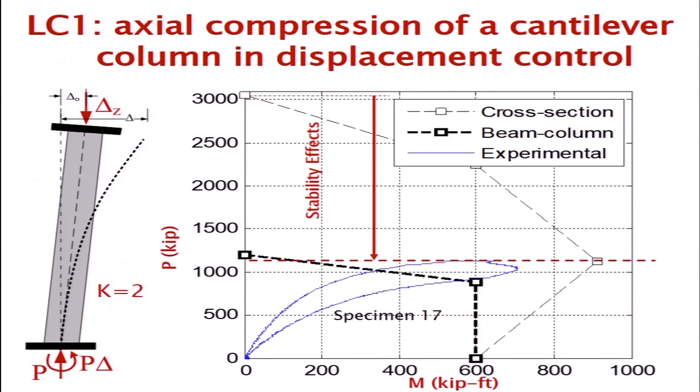And so in the case of a very slender column, right, we have a fixed base and pinned at the top. So ideally, we have something like a k equals 2. So in fact, when I was telling you that I had a column that was 8 meters long, the effective length was actually 16 meters. So this is pretty slender. Okay.